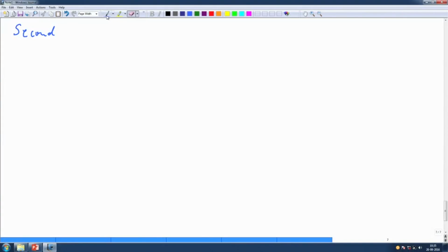So, in the previous lecture we have seen how surface tension is defined. Here we are going to look at a second definition of surface tension. That is important. Now, if we consider it like this, the surface tension is the interfacial tension that tries to resist any increase in interfacial area. So, this is kind of a force equivalent definition. Surface tension is something which tries to resist any increase in interfacial area,